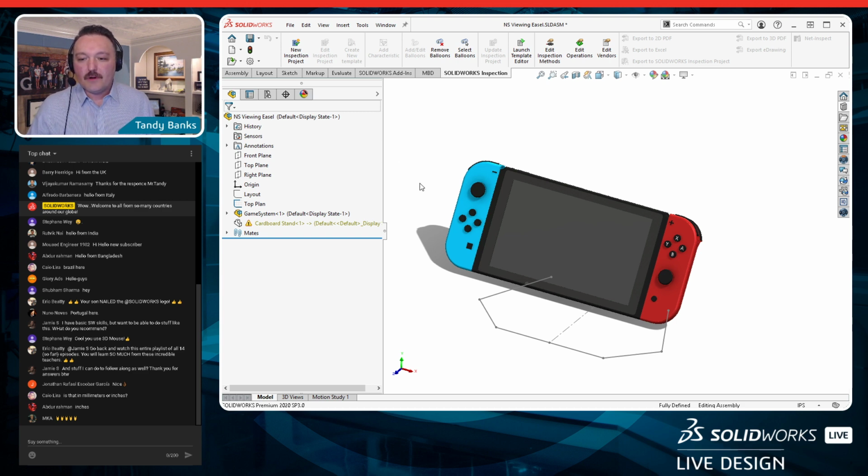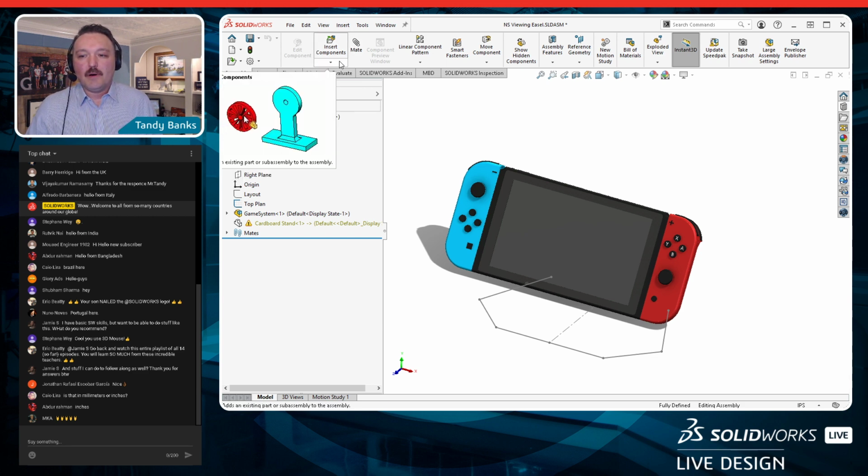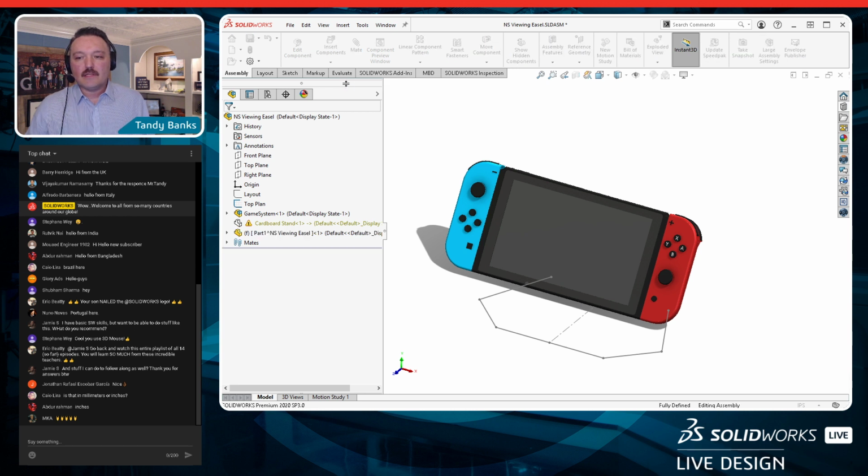All right, so from here we can get started, and in the assembly toolbar, this is where we can insert components. And a lot of folks look at insert components as a bottom-up design technique, and that's where we've got all of our components already built and we just want to assemble them. But if you use the drop down there within the insert components toolbar, we can come down and choose new part. And so I'm going to insert a new part into this assembly, and what it's doing for me there is a little flash, and it went in and inserted a brand new component as an internal component.